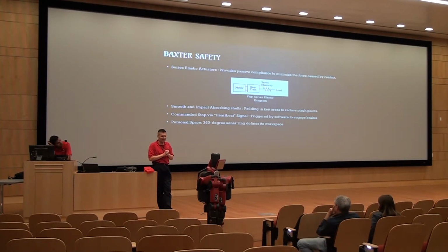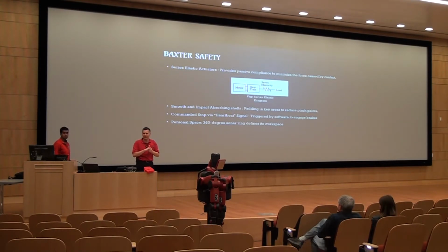Okay. I can tell you that they are allowing these to go cageless. And right now, I don't think you can purchase any collaborative robot that has more than a 10 kg load limitation. I think until the standards are further developed, that's probably the space where it's going to remain, at these very low payloads and relatively low speeds. Are we going to see this being a welding robot? Probably not in the near future. But as I mentioned, the typical material handling types of applications, it's well suited for. Many parts are under those 10 kg limits anyhow.